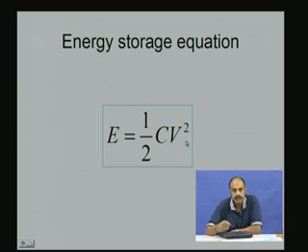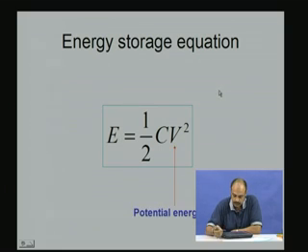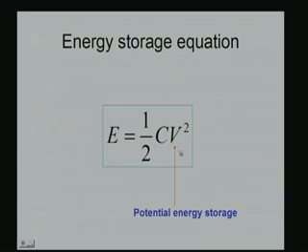We know that the wattage is V into I, and V into I into time is going to be the energy, watt seconds. So, the integral of that over a period of time will give you the energy, which is as given here. So, we say that as the capacitor has the voltage variable in the energy equation, its state variable, or the history that it can remember, is the voltage, which is the potential, and therefore it is called the potential energy storage component.